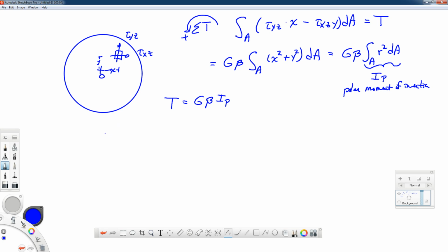The only one that we really have to take a close look at for equilibrium, again, we're neglecting body forces, would be the equation that looks like the partial of tau xz with respect to x plus the partial of tau yz with respect to y plus the partial of sigma z with respect to z equal to 0.